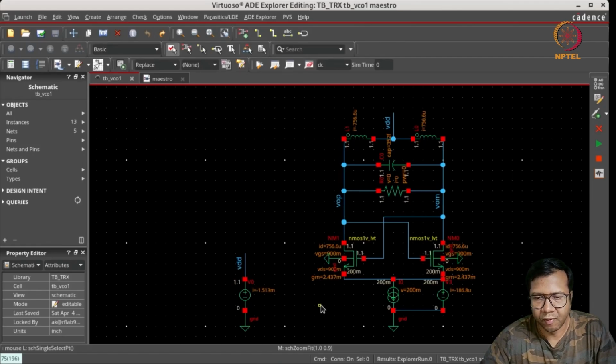So in this case, if we want to increase the startup gain for the same RP, we have to increase the value of GM. And if the current is also fixed, then one way to increase the GM is by reducing the VDD. Since we can see that in this circuit, VDD is directly deciding the gate voltage and the gate overdrive. Let's say we are not touching the headroom which is given for the tail current. Then in such a scenario, by reducing the VDD, we can reduce the gate overdrive. And for the same current, we will be able to improve the GM.